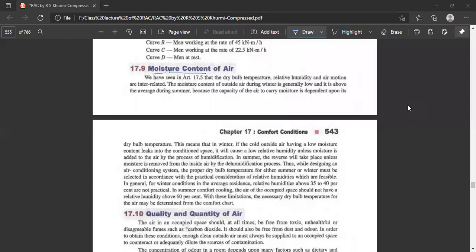Relative humidity, for an air and water vapor mixture, is the amount of moisture actually contained in the air, in grams or kg, divided by the amount of moisture which would be present in that mixture at the same pressure when fully saturated, that is, when the volume of the mixture is filled up with the maximum amount of moisture it can hold.